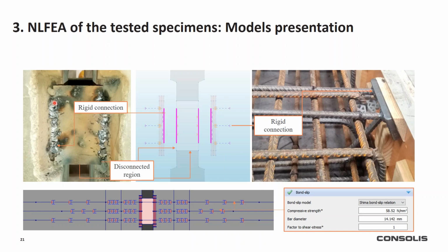We had welding, and the welding is quite complicated. For our purposes, we weren't interested in a very detailed understanding of the local behavior, so in the model I used the rigid connection options to model these weldings.